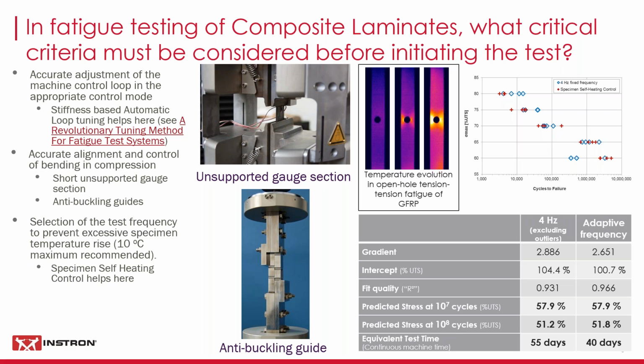This is an algorithm to control the frequency, and it will modulate the frequency, reduce the frequency to limit the specimen self-heating. The advantage of this is that rather than choosing one safe frequency, which has to work for all stress levels, you will have an optimized frequency at each stress level, and that will improve the overall test efficiency and increase the machine utilization, as you can see in the table, where a 55-day test time was reduced to 40 days, which is significant.